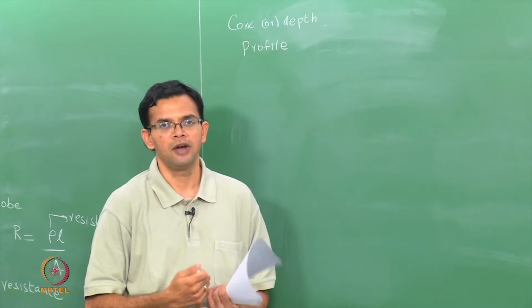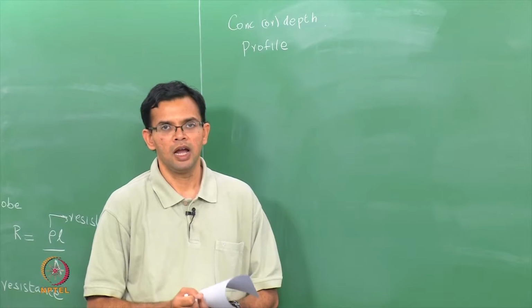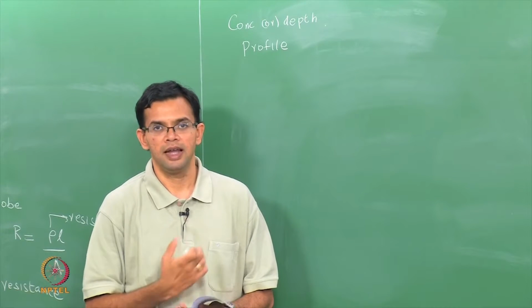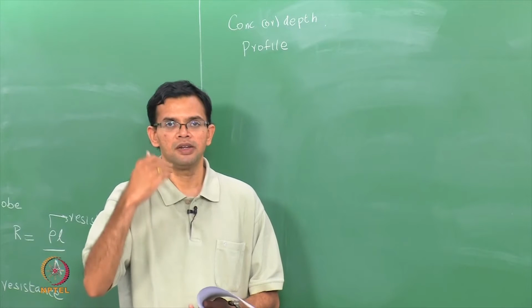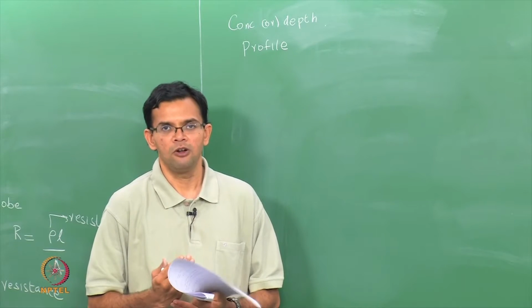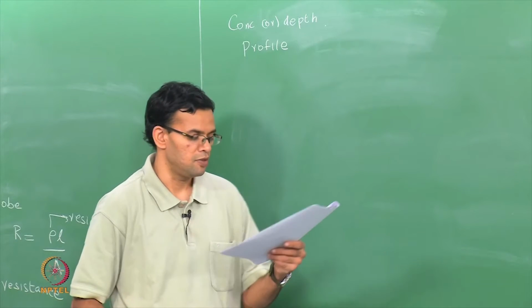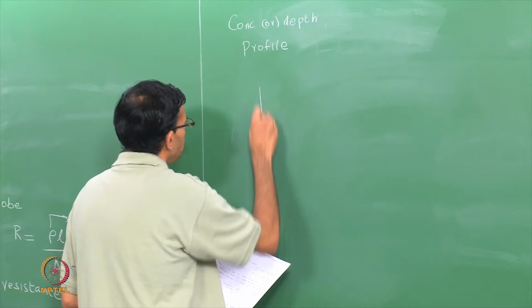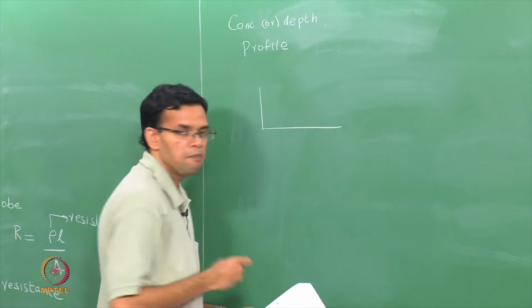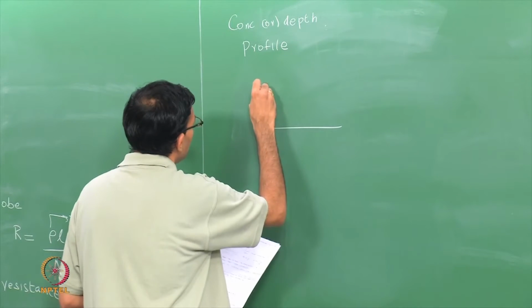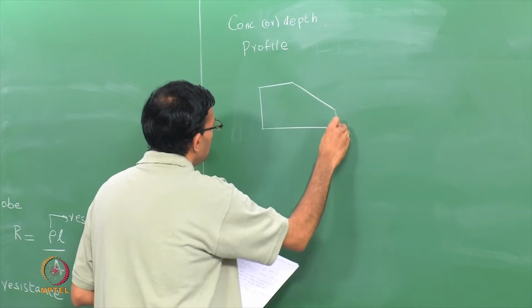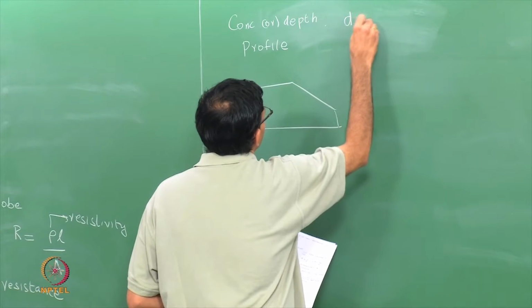For example, if you have a p-type material and you dope a certain region that is n-type, we can measure the depth of the n-type region and also the depth of the p-n junction by looking at electrical resistivity. This is again usually done by creating a bevel on the surface, so that this is usually a destructive technique.